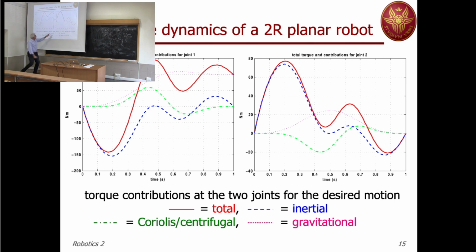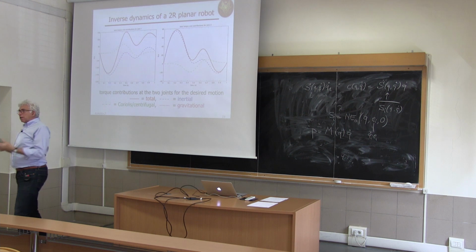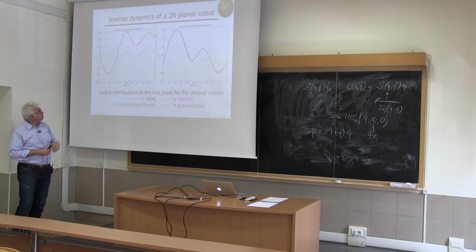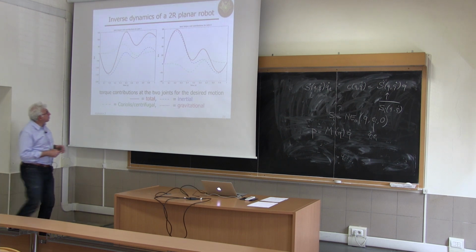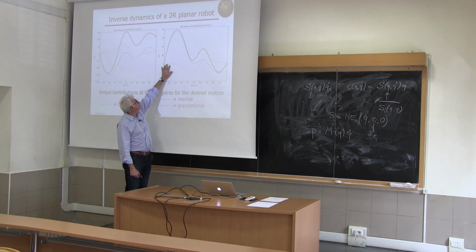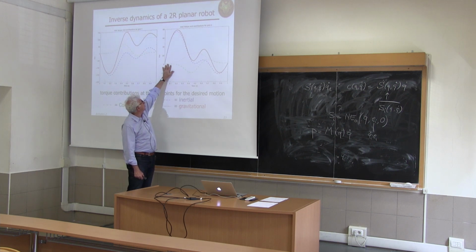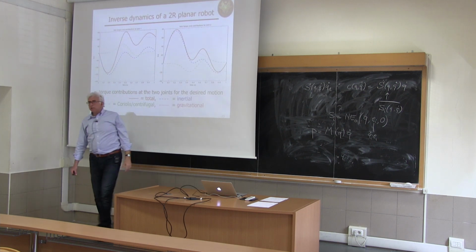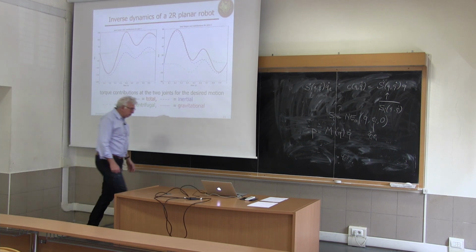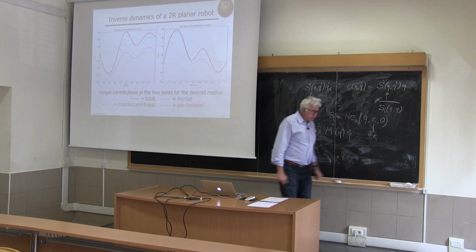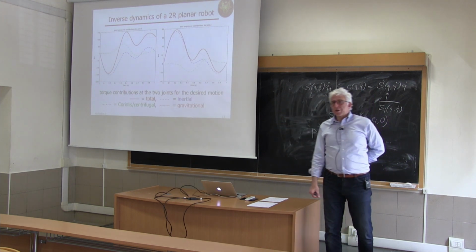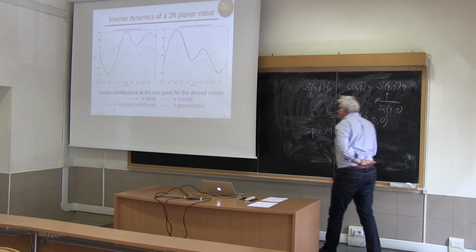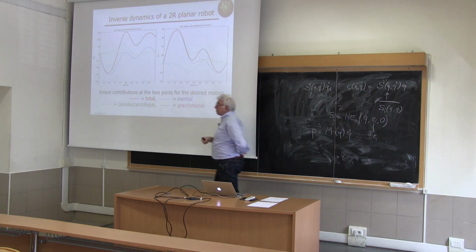And you can see that there's a large phase, for instance, for joint 2, in which most of the torque is given by the inertial contribution, because the acceleration grows and then covers most of this effect. In the first few instants of time, velocity is low, gravity is almost 0 in that configuration, so everything is given by the presence of an acceleration, and so on. So you can argue about the composition of your total torque.